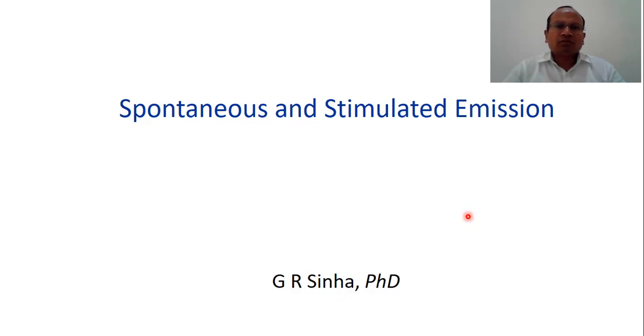When we talk about optical sources, which are energy sources of light, generating the light signal used in optical communication systems: in an LED, the emission is spontaneous, and in a laser, it becomes stimulated and very powerful. So in this lecture, we will try to understand how stimulated emission is different from spontaneous, and how stimulated emission is more powerful, having more directivity and a narrower wavelength.